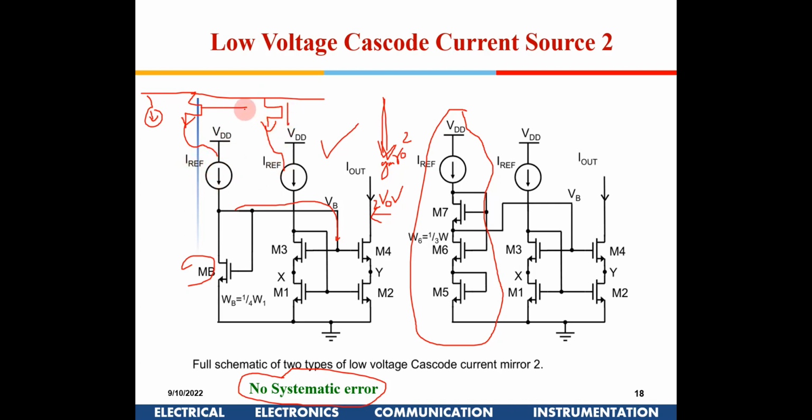So in the whole VLSI circuit there will be only one I reference, and with that I can have n number of branches. But obviously the penalty is a little bit more area, more number of transistors, more power. So obviously the penalty is there. Nothing comes for free in either digital or analog. There will always be some trade-offs between different figures of merit.